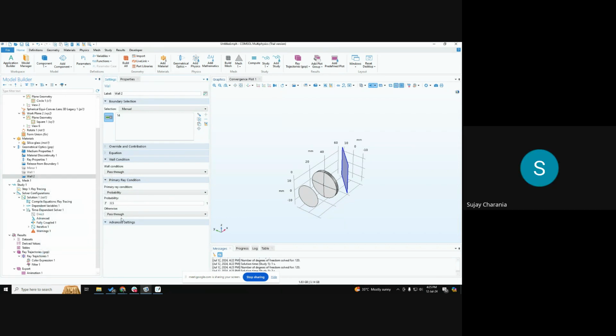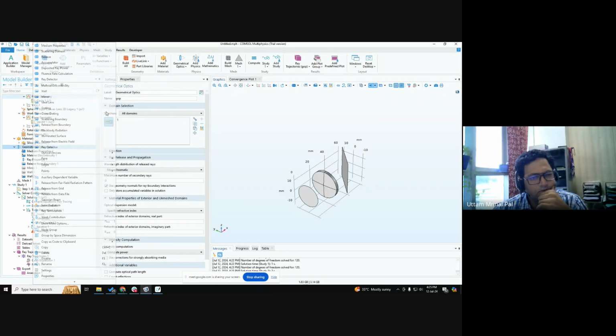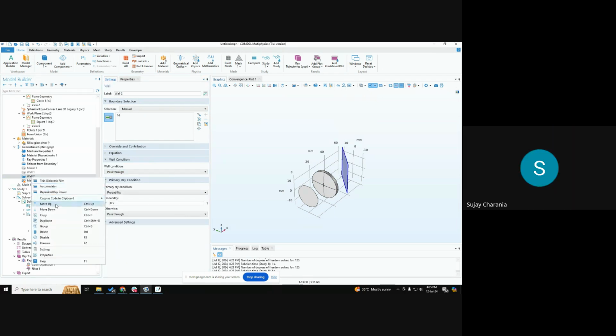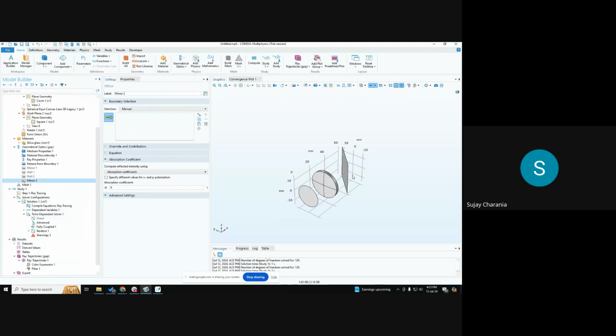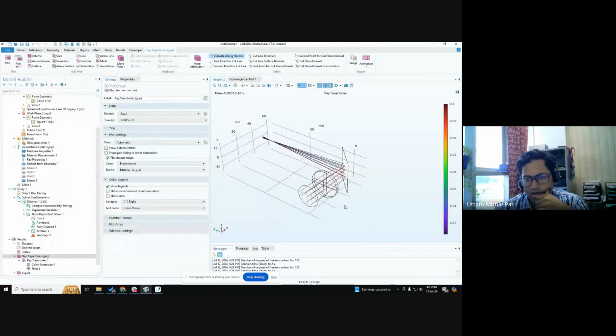But can we then, in this case, play with the mirror property? Not a 100% mirror effect, but rather 50% transmittance. From a fabrication point of view, if I have, let's say, a 200 nanometer aluminum layer, it would 100% reflect, then a 100 nanometer layer would have partial reflection and partial transmittance, right? I don't know. We can check it.